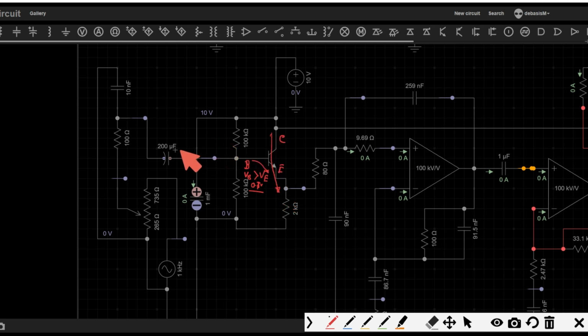So what this circuit is doing here is, one signal voltage is coming here and getting fed to this base point, and the base point is properly biased by taking voltage. I talked about the voltage source earlier. Here I have considered only a 10 volt single voltage as the voltage source. That 10 volt is divided by the 100 kilo ohm resistors here. So effectively it's giving a voltage of 5 volt here, because if you go by the voltage division rule, it becomes 5 volt here. Now here is a 5 volt.